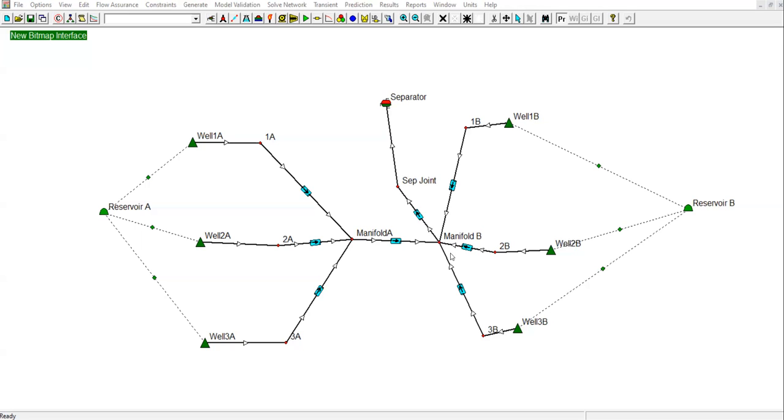There we have the data: the upstream pressure is 480 psig, the upstream temperature 97 degrees Fahrenheit. We also know the liquid rate, 17,250 stock tank barrels per day, and then the downstream pressure, 340 psig, water cut 47%, gas oil ratio of 800 SCF per STB, oil gravity 37 API, gas specific gravity 0.76, and lastly, water salinity of 23,000 ppm.